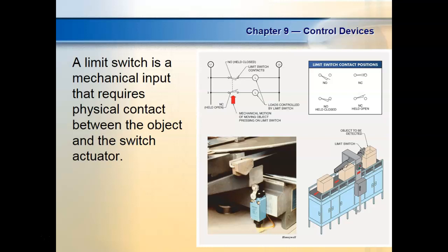So these guys are still out there. They're all over the place. They're a lot cheaper than a lot of our solid state limit switches, and you'll see a combination of these. If I can get by with using one of these, I'll use one of these. If I can't, then I'll use something else. Like if it can't make contact, then I can't use a limit switch. The limit switch is what we call a contact sensor, as opposed to non-contact sensors.